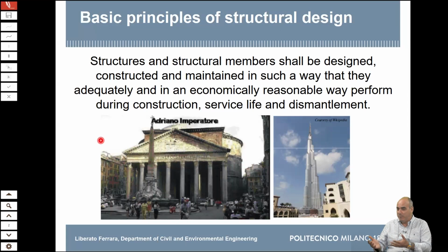For this reason, we put reinforcement. But also in domes and in shells, there are some tensile stresses, especially at the edges. And in domes, what happens is that there is a part of the dome, the bottom part, where the hoop forces, because of gravity loads, this structure just withstands its gravity loads, the hoop forces can be tensile.